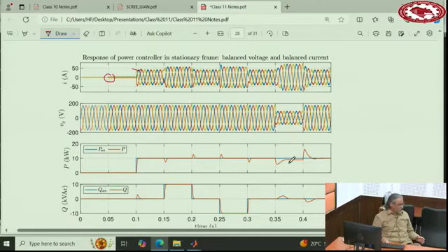Yeah, but you limit. In other words, the set point is given based on the fact that it's normal operation. It didn't know that a fault can happen. So if it's normal operation, it says, I would like to feed 10 kilowatt to this grid as long as everything is normal. But now the grid voltage drops like 50%, right? So if I want to still supply 10 kilowatt to the grid, my current will be 80 amperes. However, the switch can only tolerate 70 amperes. So I have to clip the current. So the power goes down.